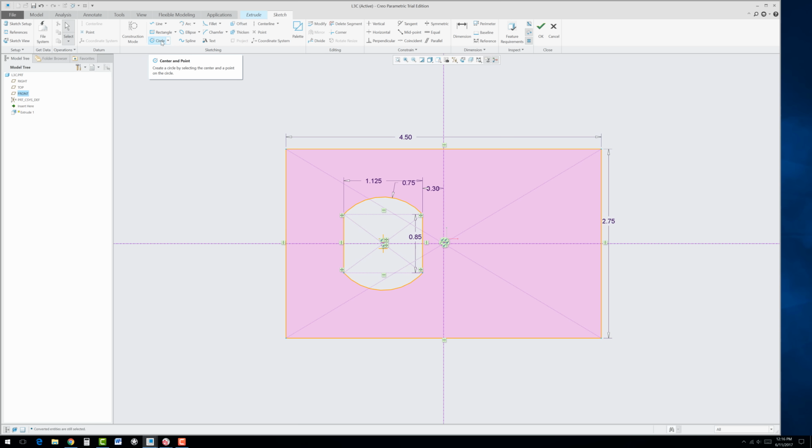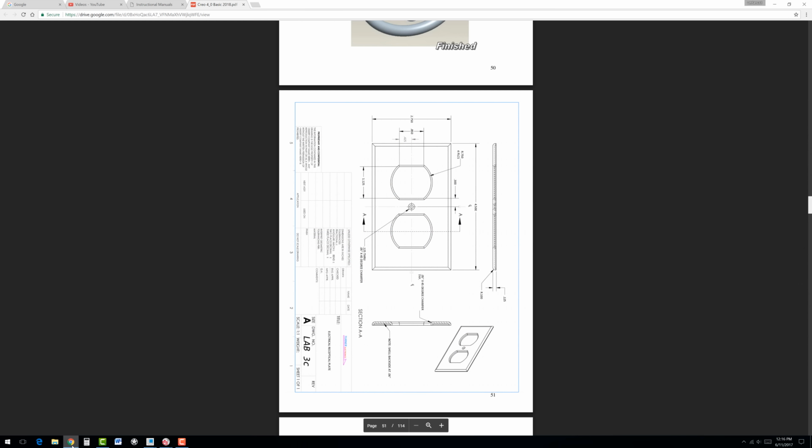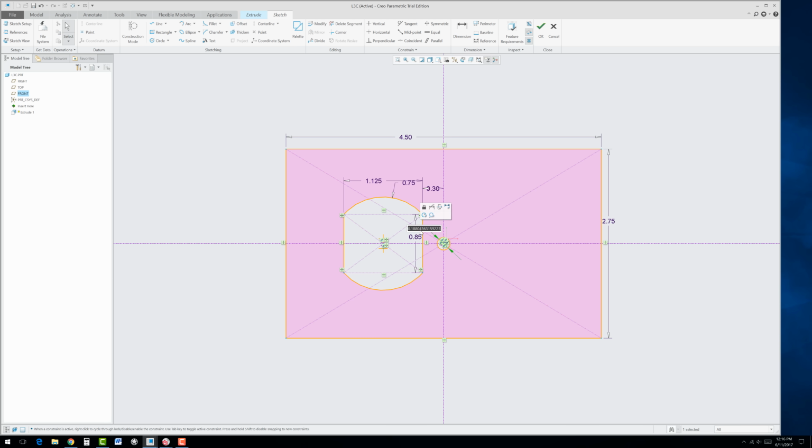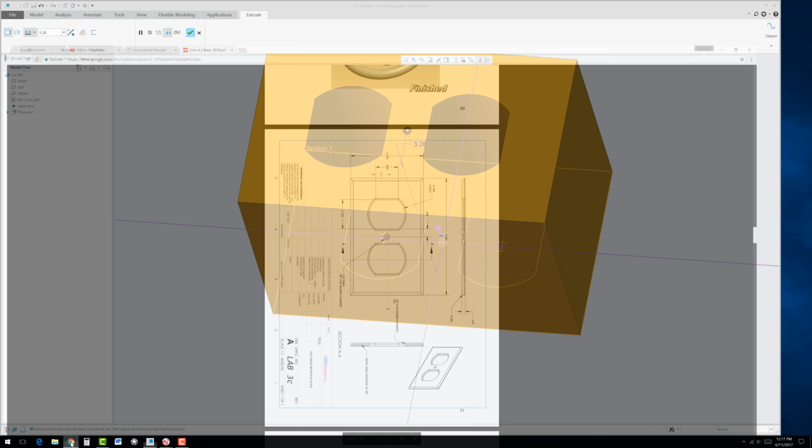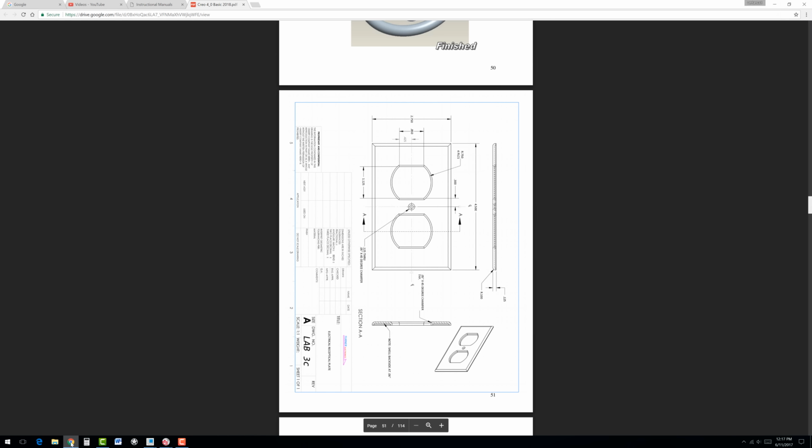Also, we could put the through hole in, and according to the print, that needs to be 0.125 through. Later it gets a chamfer. Beware the mating piece to this, actually, that 0.125 I left off the drawing, so I got to correct that. Okay, so now that we have this, let's go ahead and select the geometry we want to mirror. Select mirror and select the vertical center line now. And there we have it. We could go ahead and extrude it, and the overall thickness of this will need to be 0.125, as you can see right there.